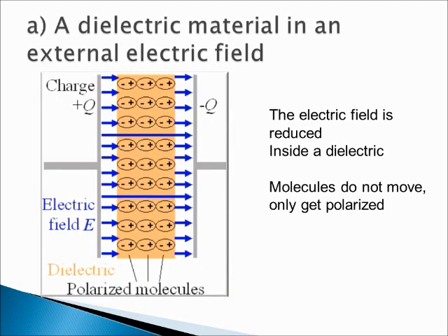Suppose we first focus on dielectrics. In dielectrics, almost all protons and electrons are bound in tightly connected molecules. It is very hard to separate protons from electrons, so there is little free charge that can be used to create the current. So when an electric field is applied to a dielectric, the main effect of the field is to polarize molecules, to separate the charges by a small distance without breaking bonds in the molecules. The molecule as a whole has no electric charge. Therefore, it only gets polarized by the field but doesn't move an appreciable distance.